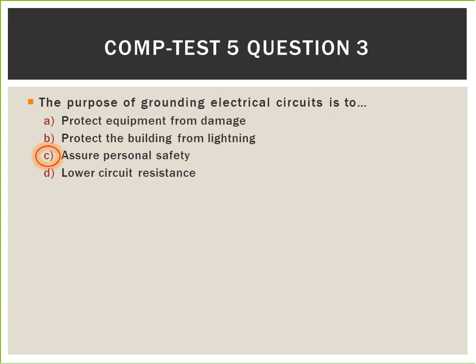C is the best answer here. Grounding is the connecting of electrical equipment and wiring systems to the earth by a wire or other conductor. The primary purpose of grounding is to reduce the risk of serious electric shock from current leaking into uninsulated metal parts of an appliance, power tool, or other electrical devices. In a properly grounded system, such leaking current, called fault current, is carried away harmlessly. Grounding is also used in manufacturing industries to prevent accumulation of hazardous static electrical charges.